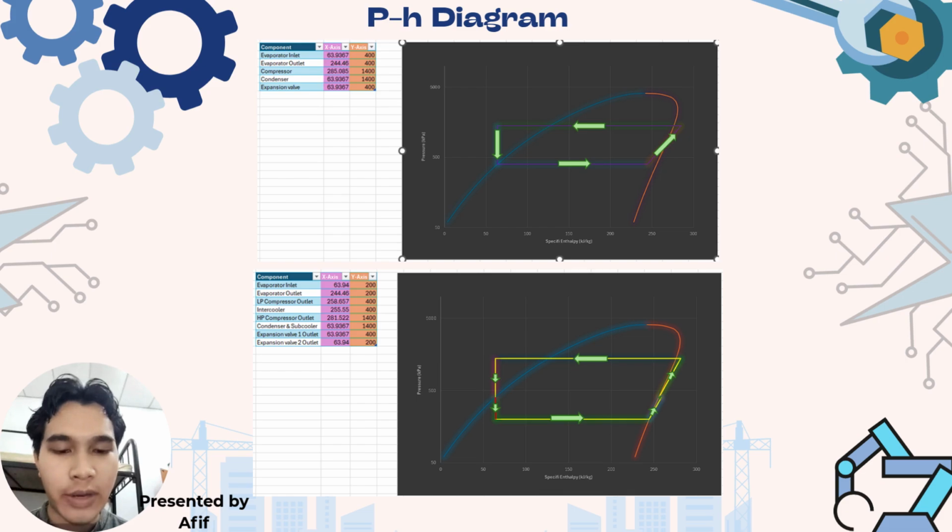And for the second PH diagram, there is also two-stage compression. As you can see, there's intercooling, like a small slight line between these two stages of the compression itself. And after the compression is done, there's also the condenser and subcooler. Both are considered as one component, and then it passes through the saturated liquid-vapor mixture region and goes down into the compressed liquid. And there are two expansion valves, as you can see from the graph, presented by two different arrows, and finally connected back to the evaporator itself.